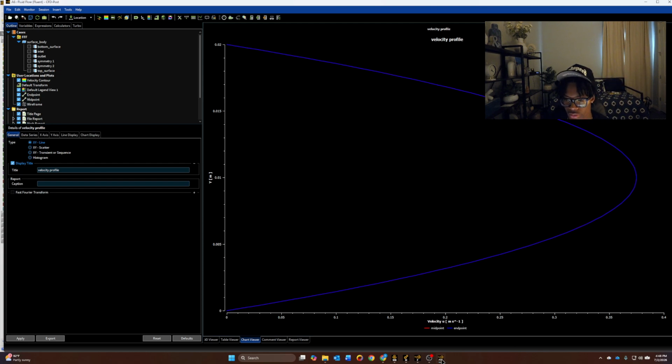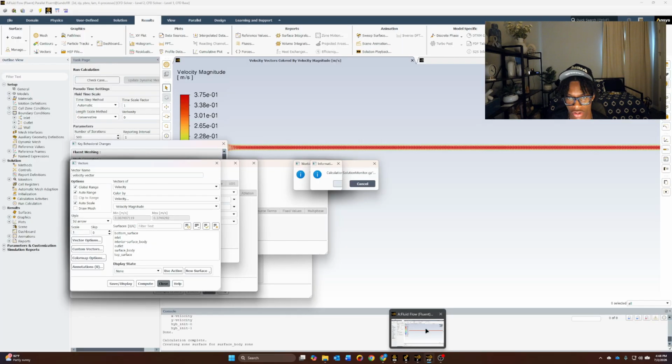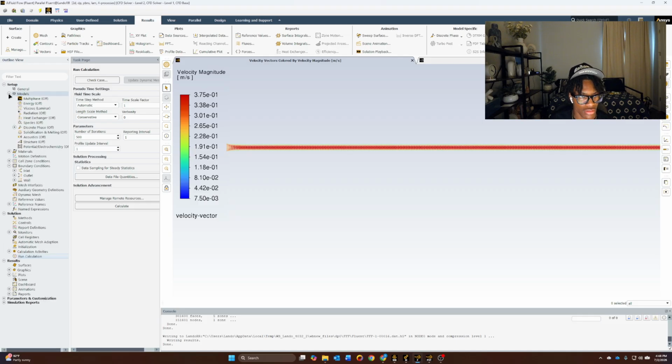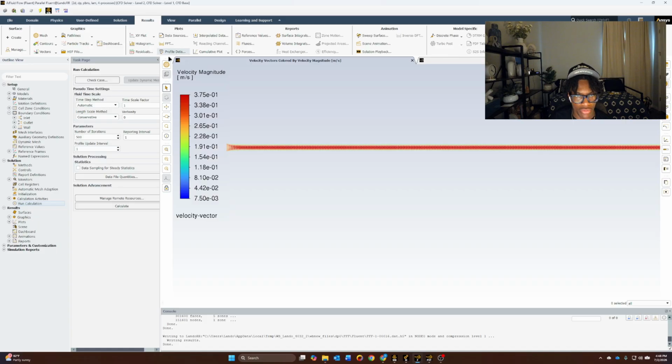And then now what we're going to do is go into our fluid simulator and basically edit everything in here. So to go to Couette flow now, we're going to go back to the fluid. We're going to first do it without touching any of the properties of the fluid. But now with Couette flow, we know that the top plate is moving with the velocity, and the fluid itself is coming in with no velocity. We're going to leave everything else the same. The only thing that we're going to touch is our boundary conditions.